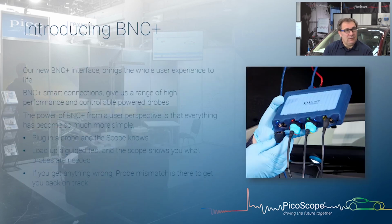So let's just have a quick look at BNC Plus. And like I said, Phil's going to start working on vehicle in a minute, so you'll really see just how quick this makes it to set up to running a test. But effectively, if you've not used BNC Plus before, what we're doing is the scope is reading what we're connecting. So the minute you connect a current clamp or a test lead or anything else, the scope actually knows. So this is much more different from a standard oscilloscope with a BNC connection where you've got to tell the software what you've connected. Effectively, the newest versions of PicoScope do that all for you.